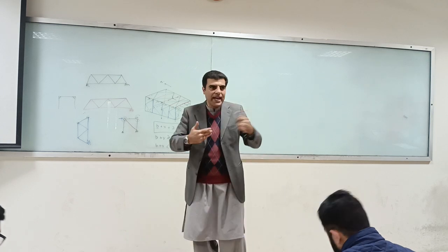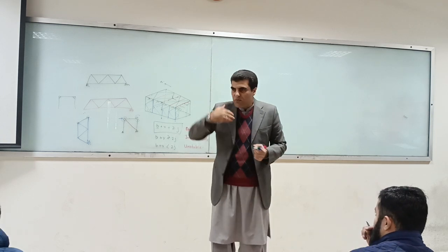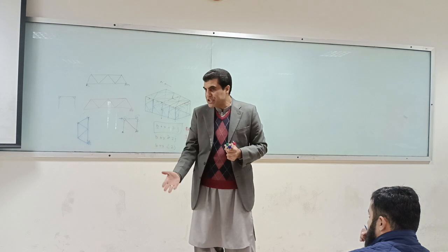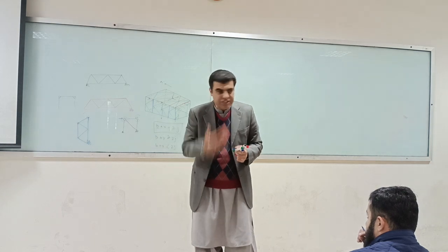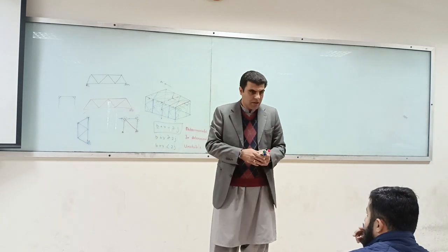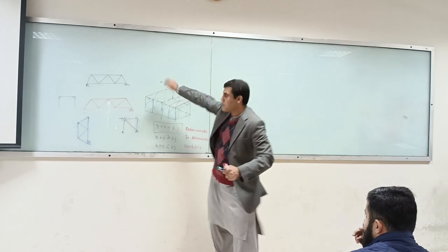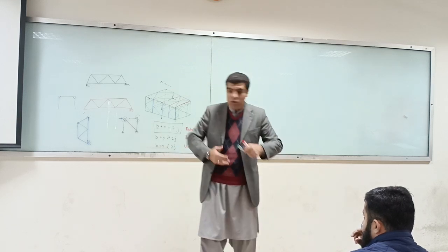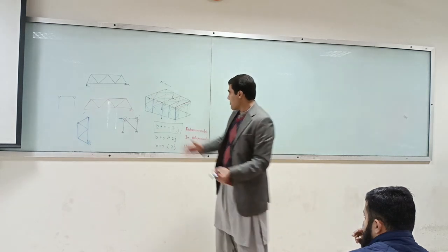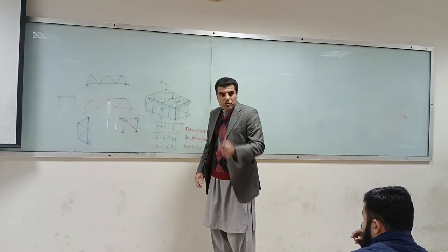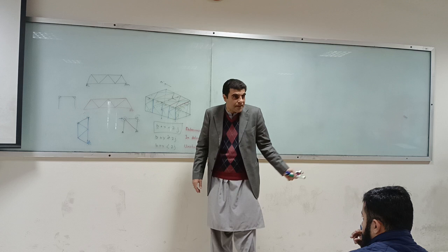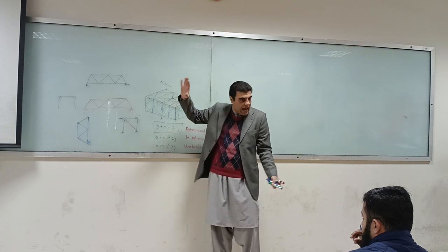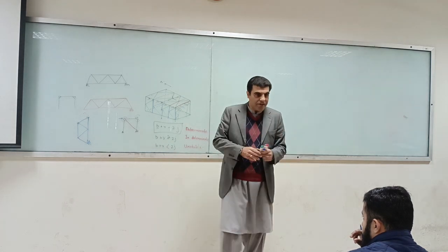If you are working in a design office and someone throws a structure at you, the first thing you check is whether it is stable, whether it's doable. You just don't close your eyes and apply some structure analysis technique and do everything, and then at the end of the day you wake up with your surprise that that structure is not working in the first place. It's unstable in the first place. So then all of your exercise is nullified.